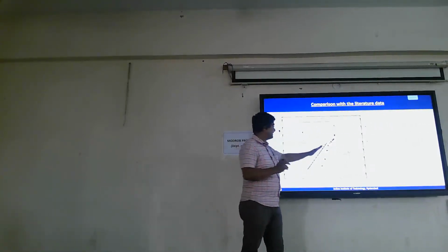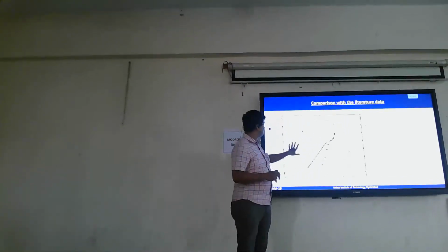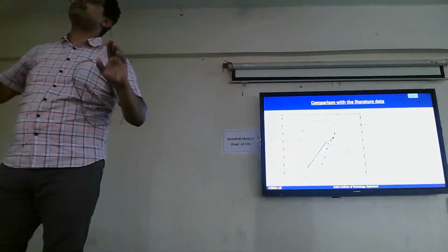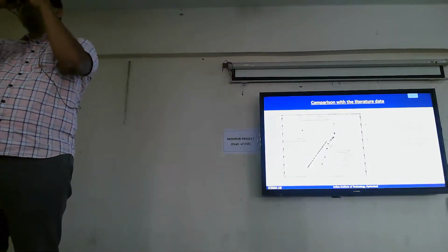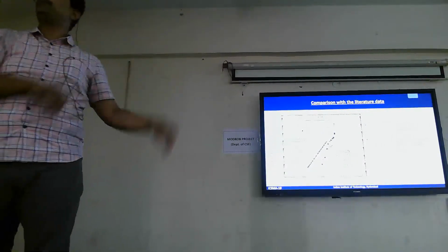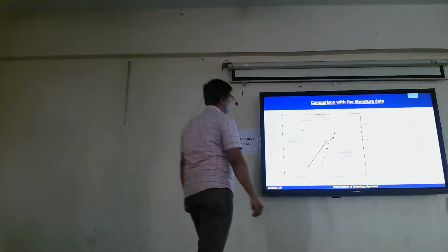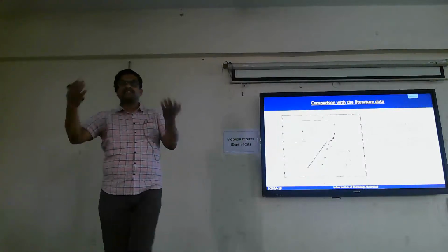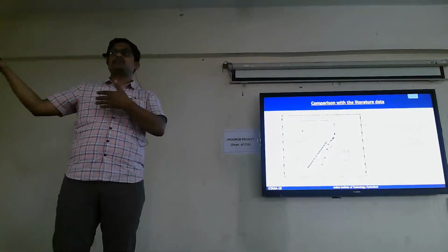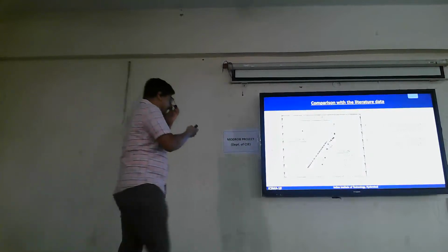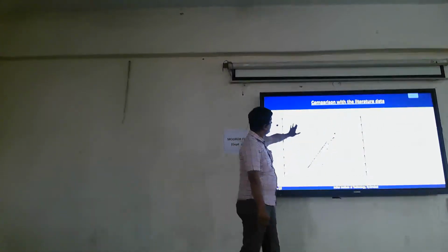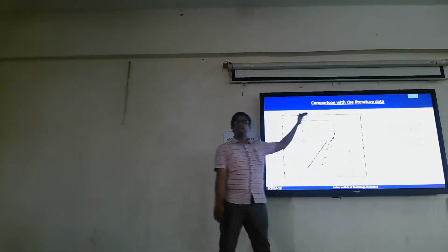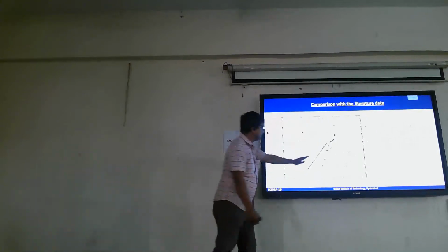I can see that our data is 2 orders of magnitude lower than the literature data. So within the comparison to 100 alloys itself, our strain rates, our creep rates, are much lower than what is presently reported creep data on the 100 alloys. We have another curve where we compare with P91 and P92, which are presently used as materials in ultra supercritical thermal power plants. Again, this alloy shows much better creep resistance. I want the curve to be as low as possible, that's why the strain rates are as low as possible.